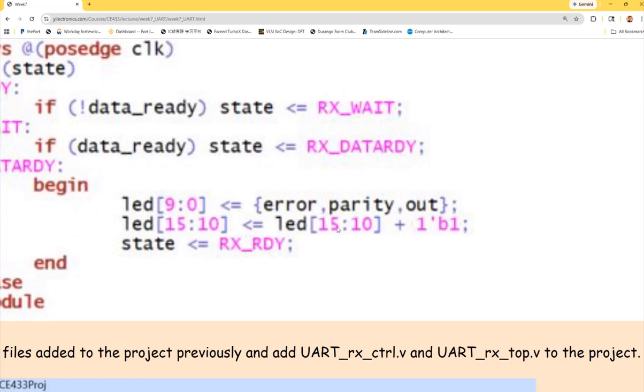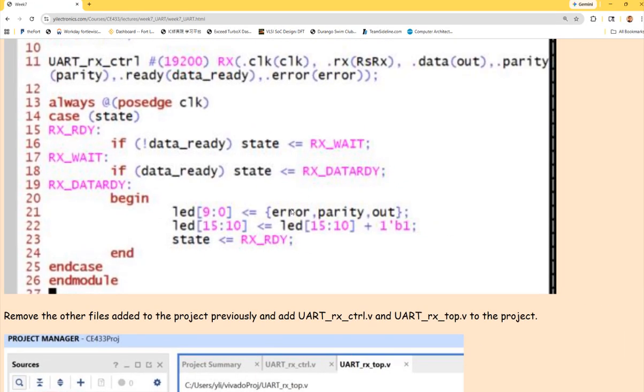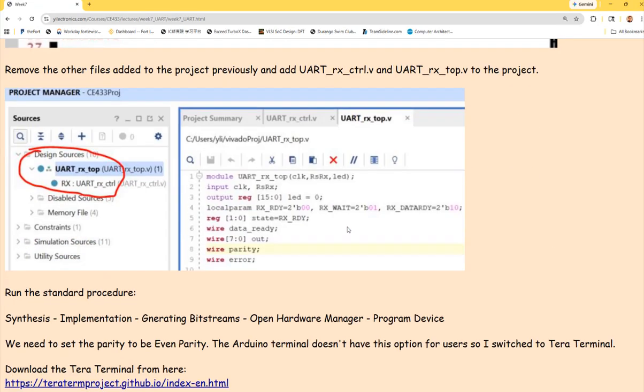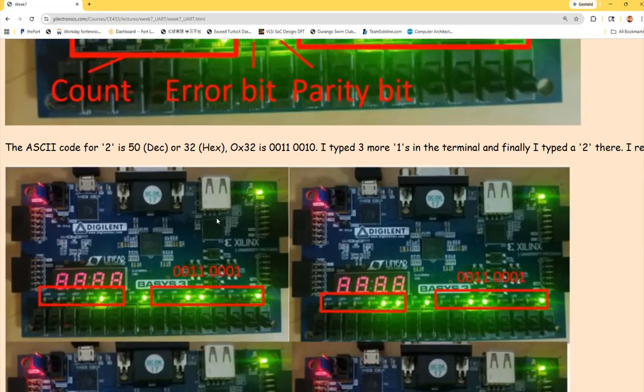So what this is doing is these 6 LEDs are indicating how much data has been received. You can see every time it enters here, it forms one total data. It increments the LEDs as a binary number by 1, right? So you can imagine it's starting from 00001, and then after it received another byte, this becomes 10.